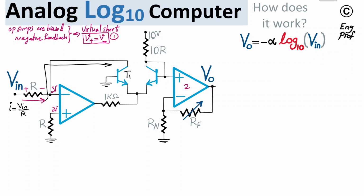It's important to note that transistors T1 and T2 should be matched. They should be on the same substrate, and they should be very close to each other so that they have exactly the same p-n junction properties and also thermal properties. That's important. So they should be in the same package, same substrate, same junction property.